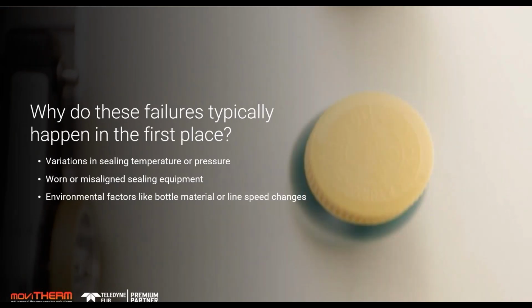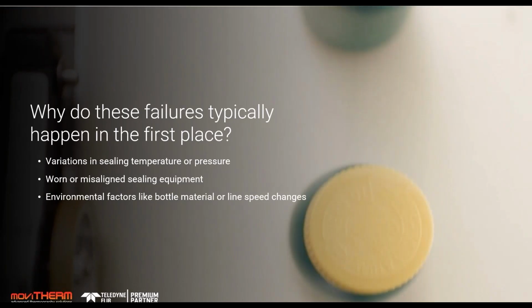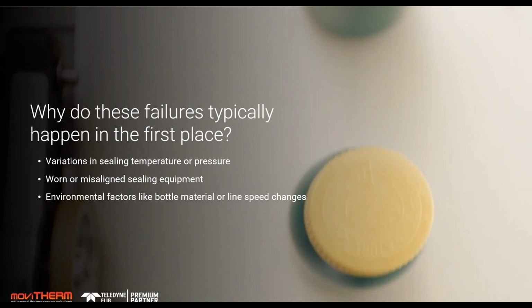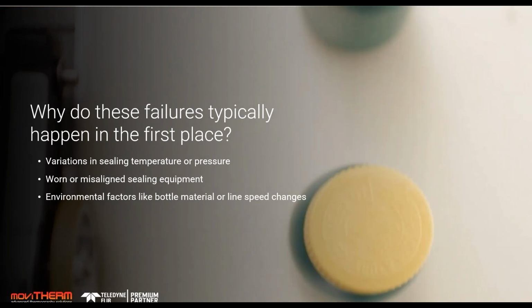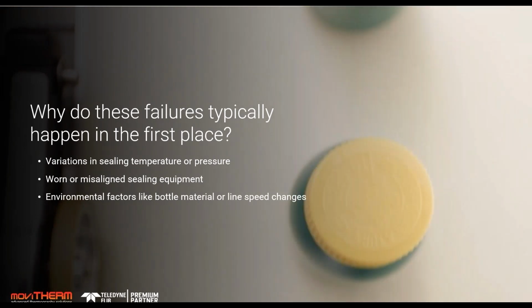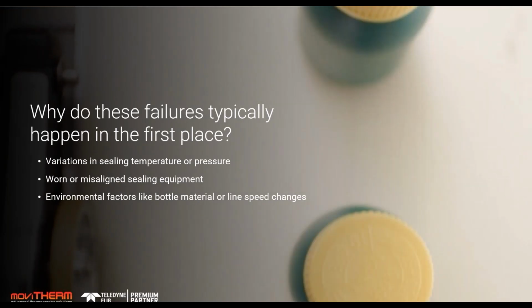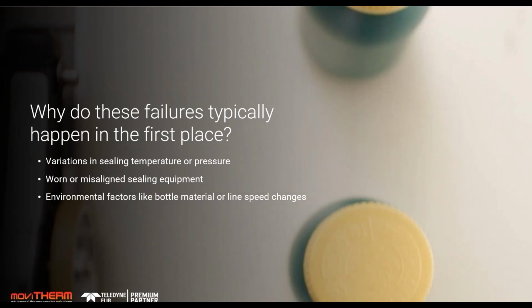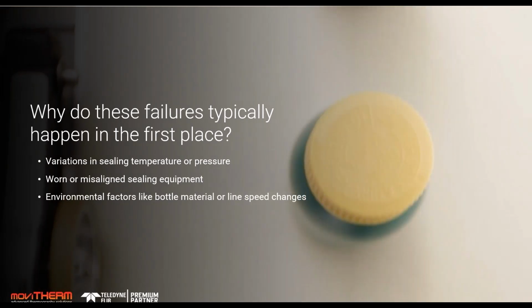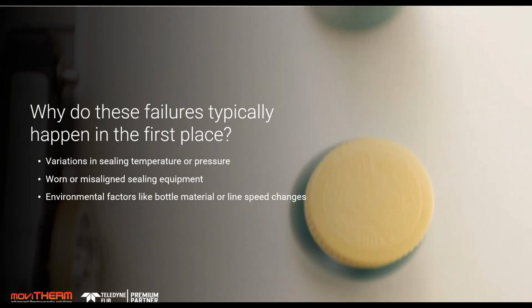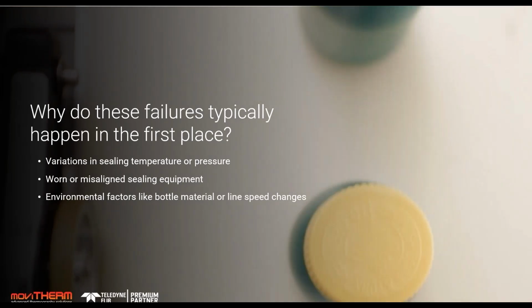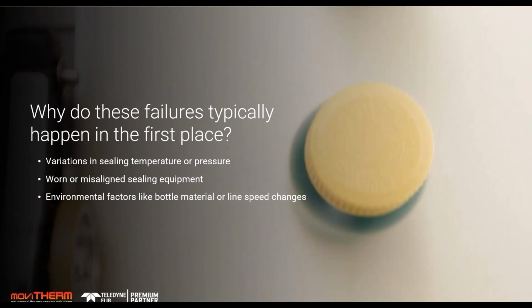So I would say that one is probably the most common that I've seen, but we've also caught differences with people. A lot of times they have different suppliers for the caps, and the caps from the molds aren't completely identical. So we had another situation where they were getting failures kicked off, and they couldn't figure out what was going on, and it was just because they didn't have the right settings, because the mold was slightly different on the cap. So in that case, we had a different recipe for the different molds, but that's how kind of gives you an idea how sensitive the system is. And they were just cranking out systems that were not sealed properly at all. They had no idea. Okay. Yeah, we definitely want to try to prevent that.